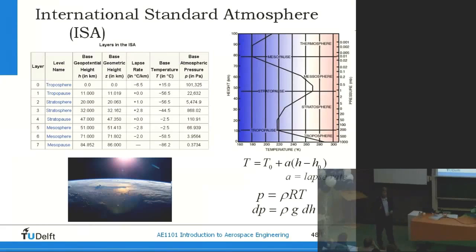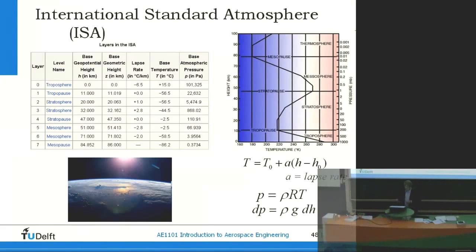So this is one of the reasons why we're able to generate lift with air. The air pressure is really immense. And normally we don't notice it because it's also pushing on the side underneath and it's on all sides, so we're used to it. But you only notice it when you have a vacuum. Even steel oil barrels will wrinkle if you take out the air. And you can see clips on YouTube showing the effect. It's really immense, the force that the air pressure around us has. So just minimal differences in air pressure will create huge lift forces already. But that's how wings do it, not how we do it with balloons.